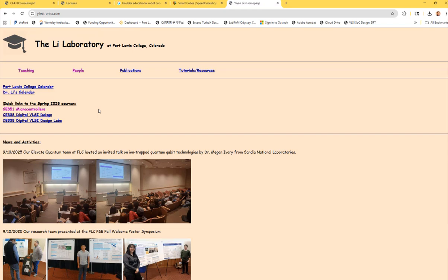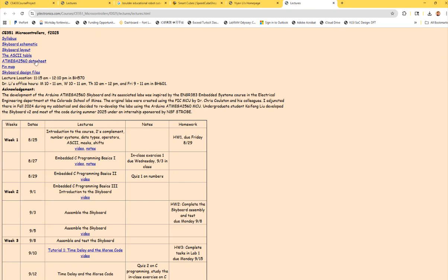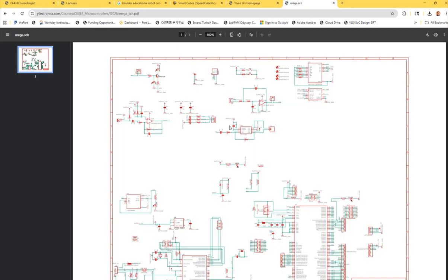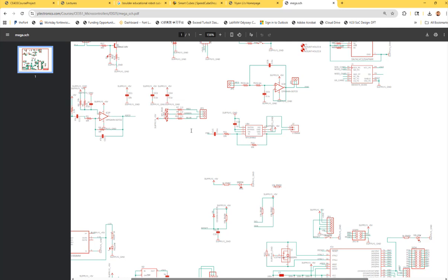You probe pin 45, and from the oscilloscope, you see PWMs. All right, so the signal is out. And then you know it's out on pin 45, and it should go to here. You probe 45, and you see it's out.